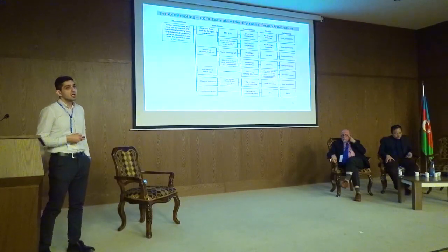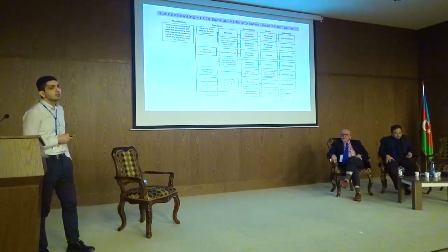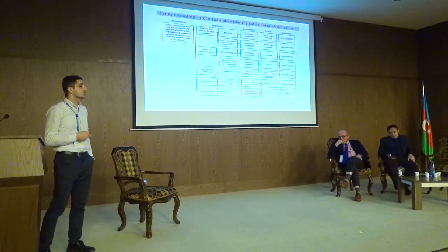Some foreign material could be somewhere between the valve and the valve seat, and it could cause less flow rate than we expected. To investigate this causal factor, we opened the turbine trip throttle valve and the governor valves, and made an overhaul inspection and a borescope inspection, and we found that there was no foreign material there. Everything was okay, meaning that this causal factor is not likely to be the root cause of this problem.